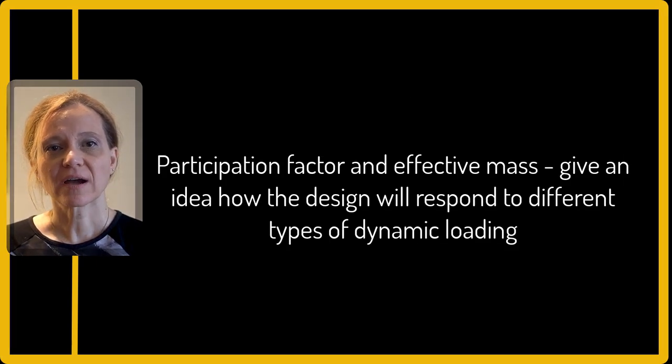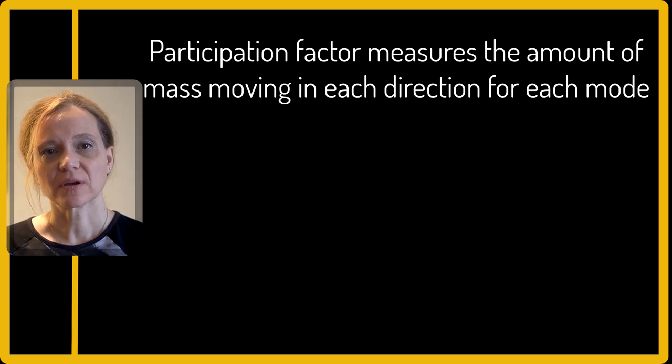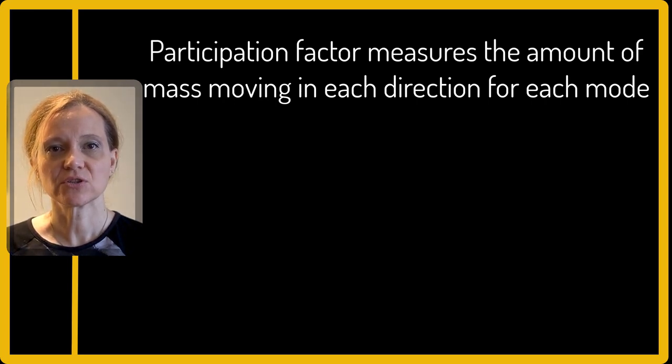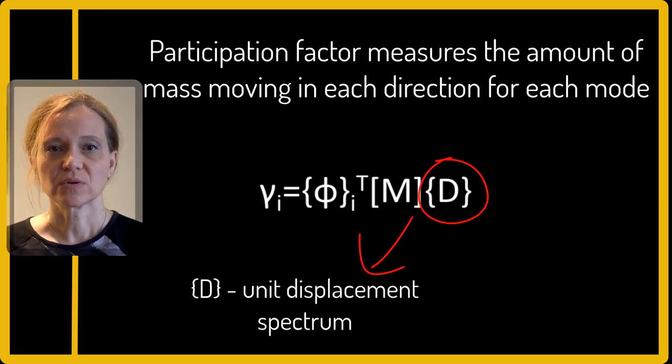The participation factor and effective mass obtained from a modal analysis can give an idea how the design will respond to different types of dynamic loading. Participation factor measures the amount of mass moving in each direction for each mode, and it can be calculated by this equation, where d is the unit displacement spectrum in each of the global Cartesian directions and rotation about each of the axes.